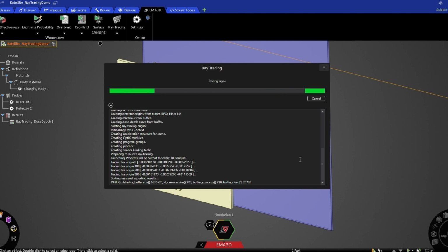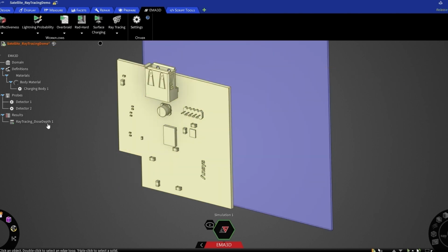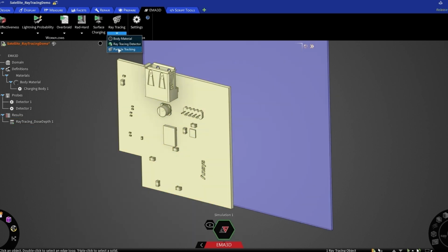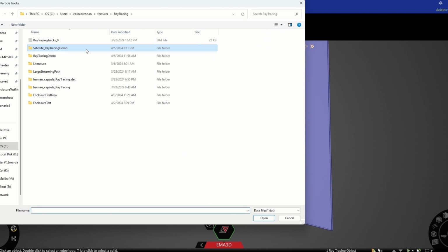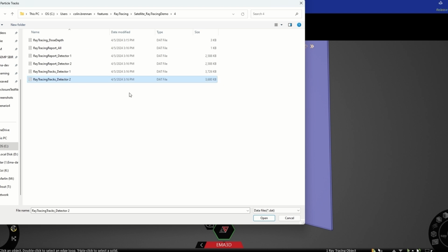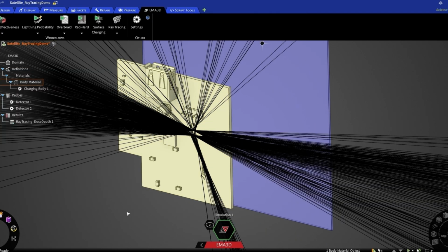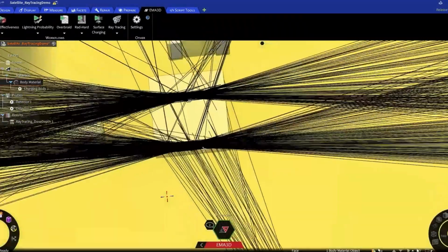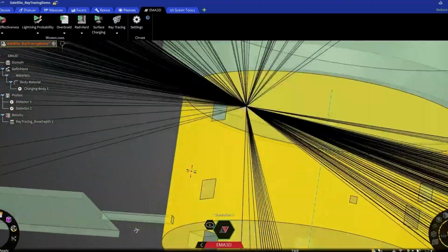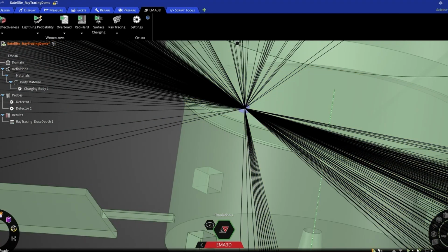We're using a GPU accelerated numerical method to get this solution and get to the value of ionizing dose on the component very efficiently. When running the analysis in Ansys Charge Plus, you can select the component and label it as a detector and define how much additional shielding you want to add on the component, or you can change the thickness of the enclosure or place the component somewhere different inside the satellite.